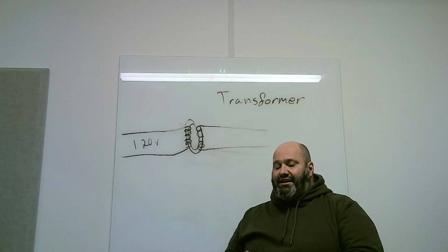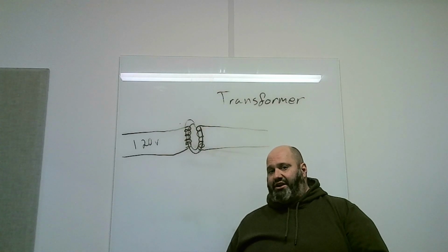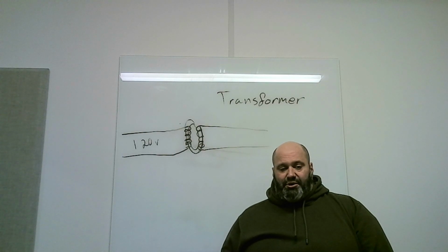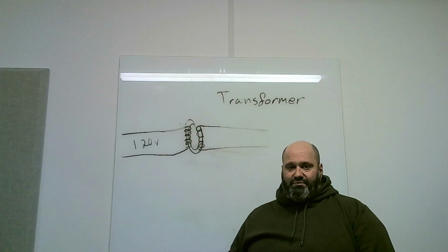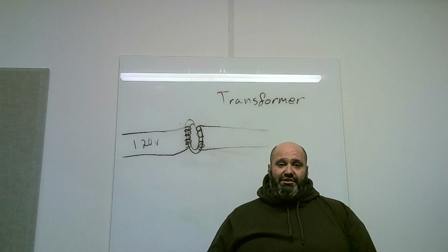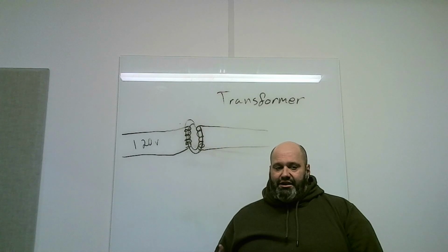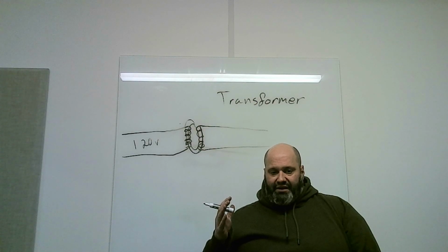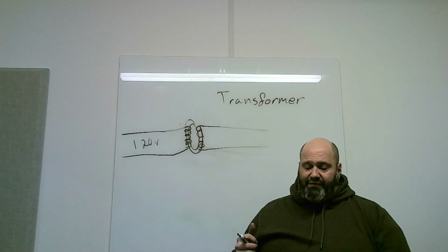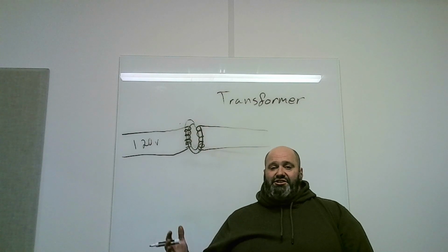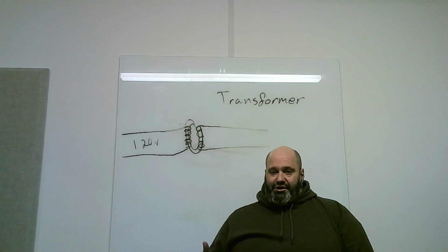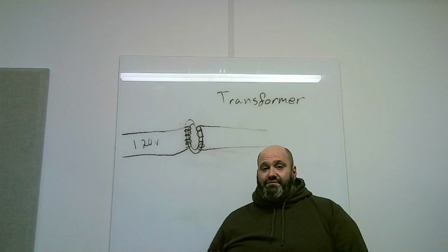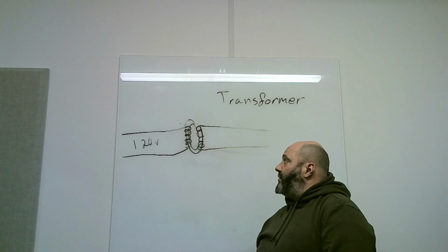One thing that I've seen, especially on older systems where maybe they're not as well protected, is frequently you will have a transformer that will blow the primary or really the secondary windings if the windings short. So say for instance on an outdoor condensing unit, maybe for whatever reason the insulation has rubbed off of a wire and it's shorted. That will actually cause the windings in here to short out and basically blow out.